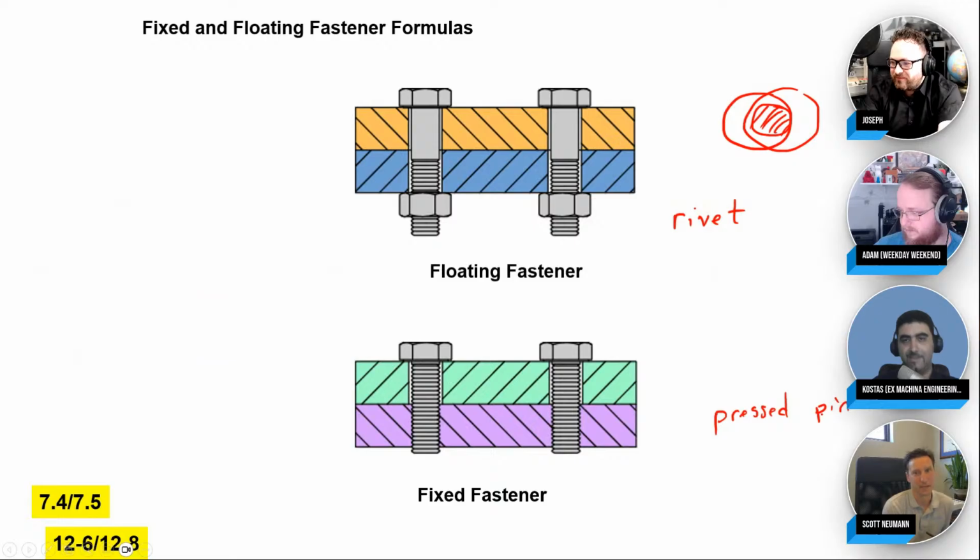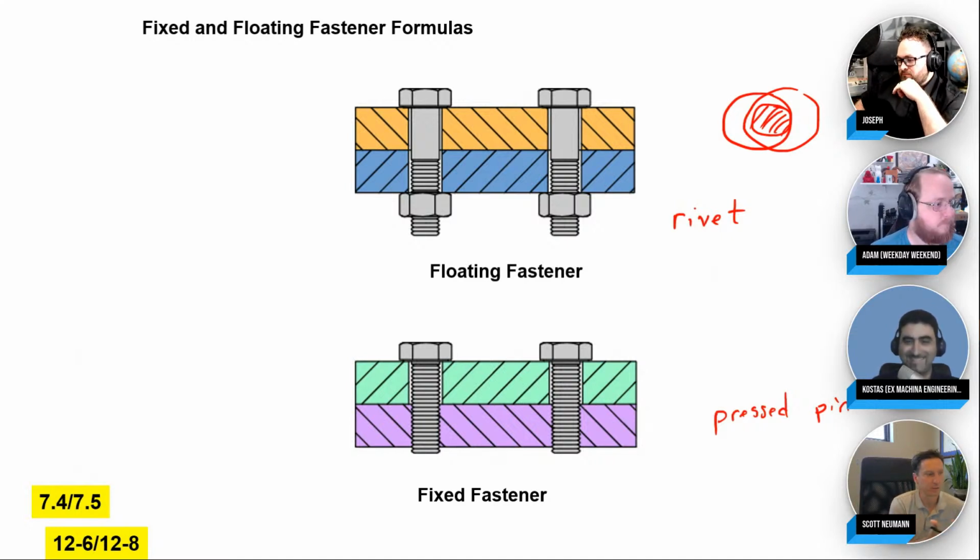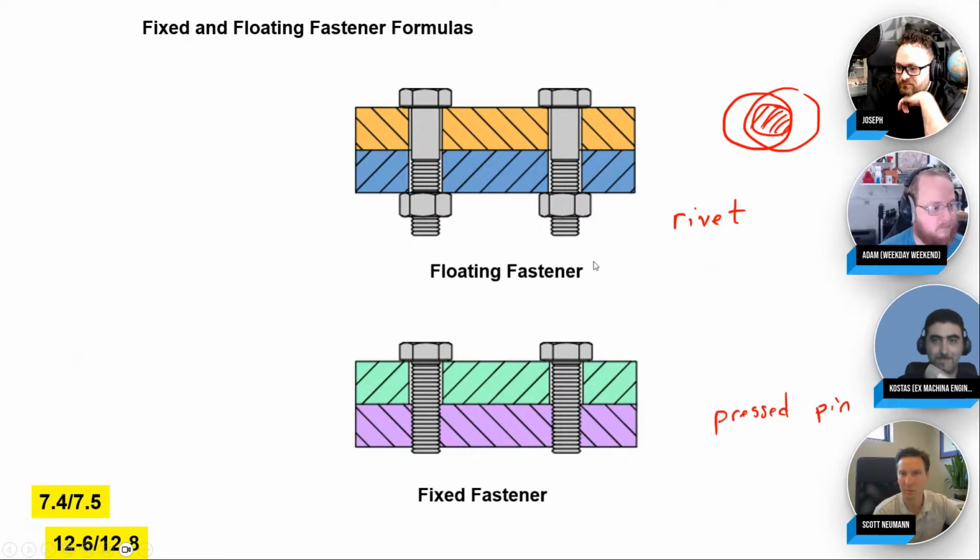Fixed. If it's fixed, welding that stud, you're definitely fixing onto the part. That would also apply to welding, like machined-in pins, a lathe pilot or something, or plastic parts with formed pins. Those would be fixed. I would say most parts are going to go together with fixed fasteners, but there are still floating ones out there too. So I would say we should learn both of them.